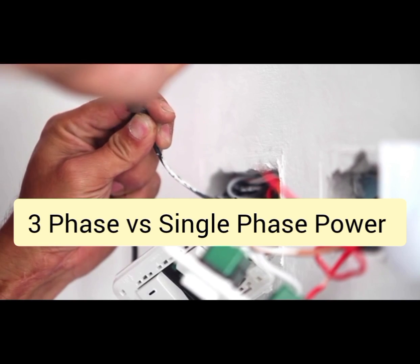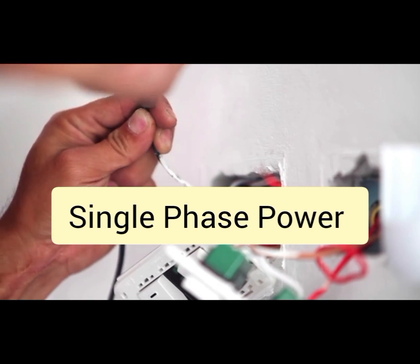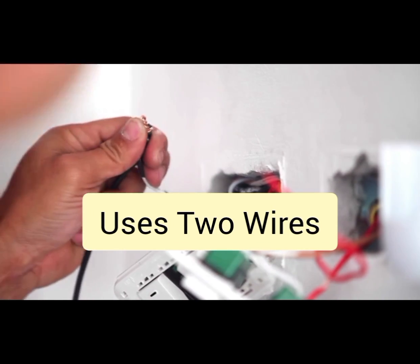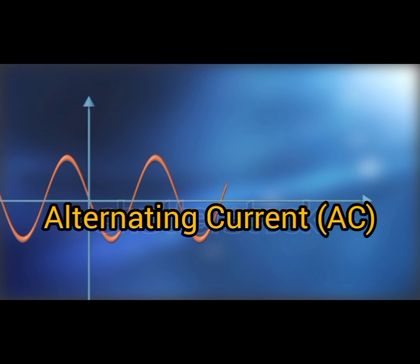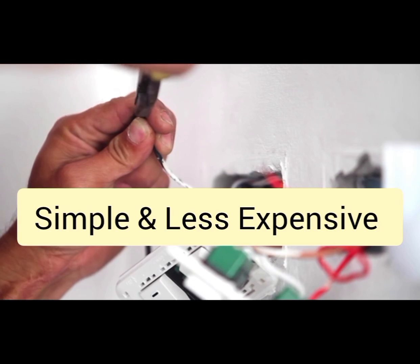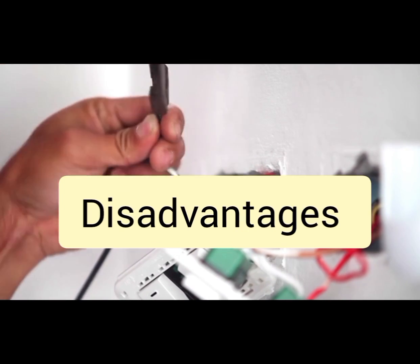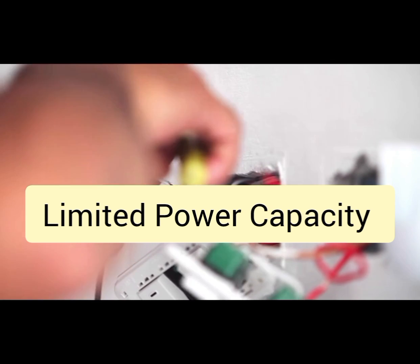Let's break down single-phase and three-phase power. Single-phase power is a type of electrical power distribution that uses two wires, one hot wire and one neutral wire, to transmit alternating current, AC. The voltage in a single-phase system oscillates between positive and negative values, creating a sinusoidal waveform. Advantages: simple and less expensive to install. Suitable for residential and small commercial applications. Disadvantages: limited power capacity. Not suitable for heavy industrial loads.